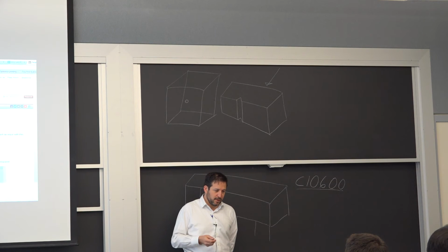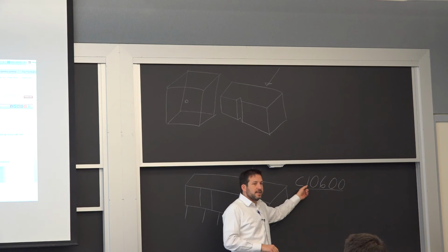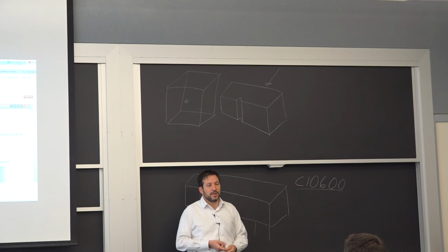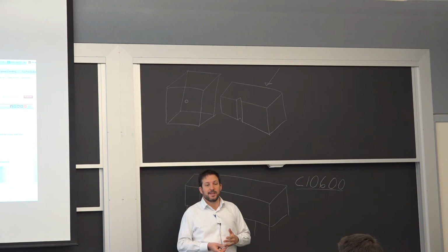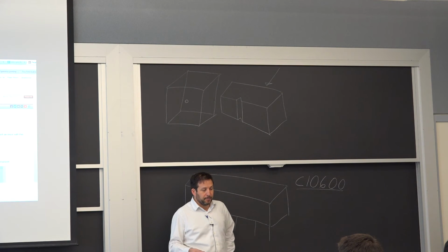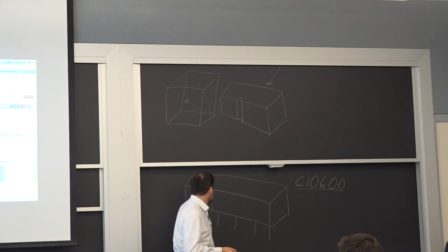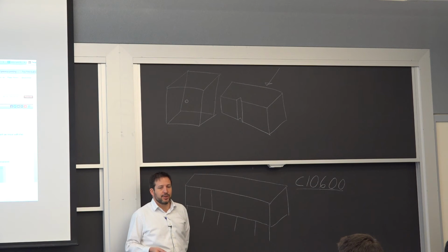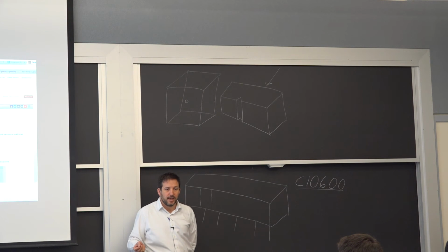Now, the real issue in a project like this, and I've seen that in other cases, is this tells you the chemistry only. This only tells you how much copper you're going to have, if you have a little bit of tin, exactly what the chemical makeup is. It doesn't tell you anything about how it's going to be cast and the type of mechanical properties you're going to get. So what happened in this case is they cast the panel without really preventing oxidation. They had a lot of residual stresses, and essentially the panels were fairly brittle.